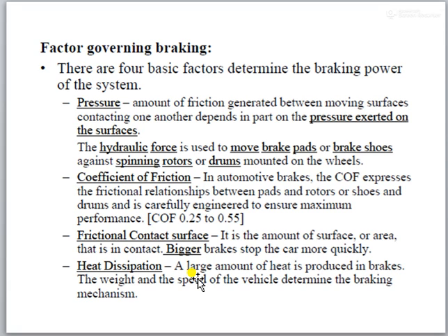Now the fins is not a good option because nowhere the fins is used, except in case of the rotor. Wherever using the disc brake, in this case the fins is used. But in case of the drum brake, no such thing is used. But in case of the drum, to absorb or to dissipate the heat early, they increase the material.